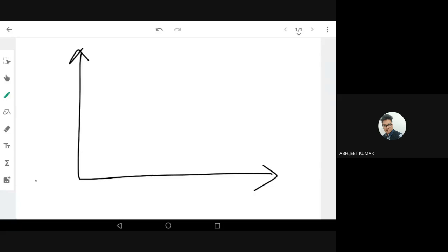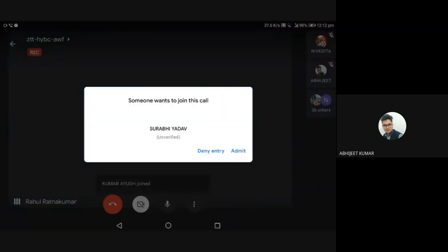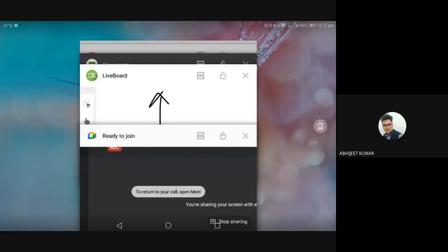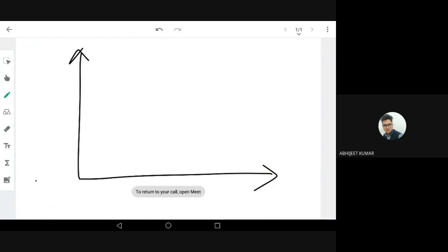When you're designing a circuit, the designer is interested in the exact Q point or operating point, so that he can know where my output is going to swing, that is IC versus VCE. But there's a chance that the Q point or operating point can shift. So the designer should know what the possibilities are, even if it is shifting, where my operating point will be lying. That is called the load line.